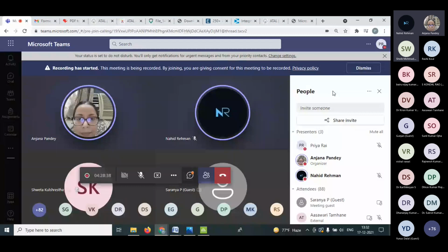This Plackett-Burman can also be done in Minitab, in the same way. First, you design the Plackett-Burman design, put the number of variables and the levels, and it will give you the run structure. Then according to the run structure, you set your experiment. Whatever experiment you are doing, it is not only for hydrogen; it can be for any experiment or product. It will compare the response with the combination. Then you optimize and see what optimization value you are getting. Based on the p value and the f value, you screen which factors are significant, meaning they significantly affect the response, and then you take those parameters for further study. Okay. Thank you. Any other?